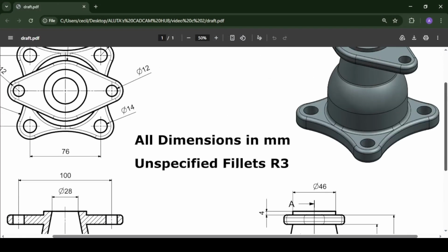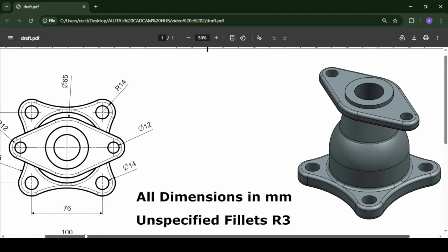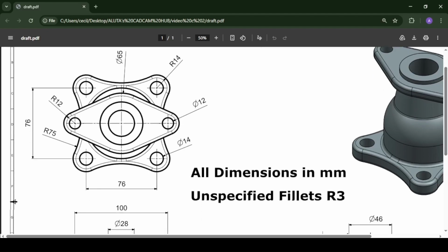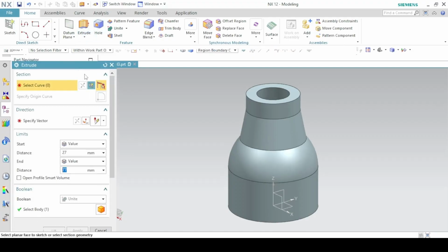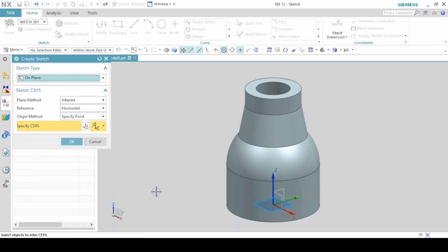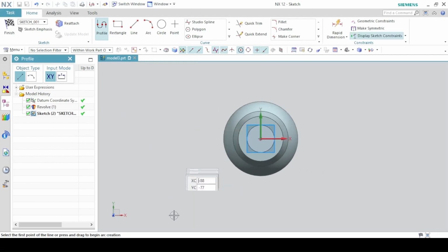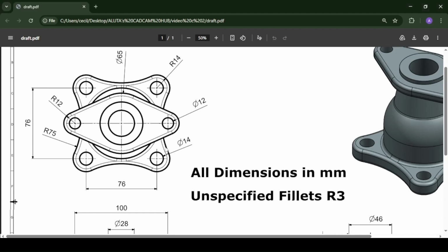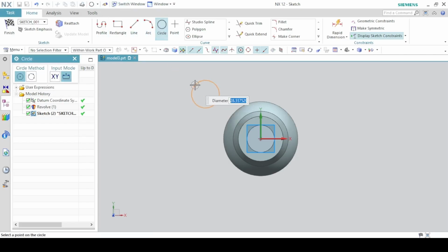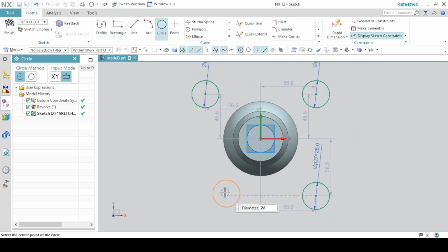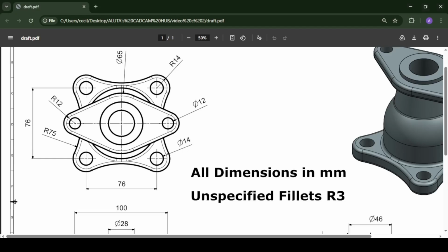We can add the bottom flange here with this sketch. So extrude, we sketch on this base plane here. We have 4 circles of diameters 14 times 2. Because the radius is 14, the diameter will be 14 times 2. So circle of diameter 14 times 2, which will be 28. The system has calculated it for us. And then inner circles of diameter 14 this time.